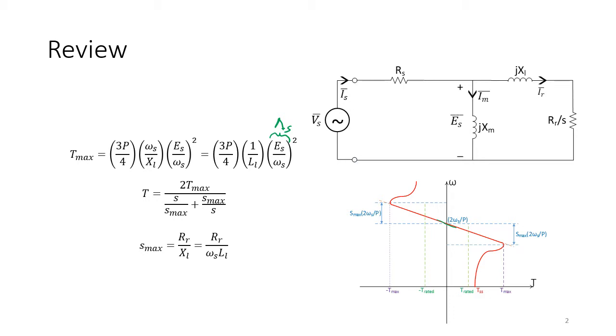Or even if it is larger but only slightly larger, your acceleration will be slow, so it takes a long time to get to the maximum torque you want. So we said, okay, one of the first issues we need to solve is how we can increase this TSS, or this standstill torque or startup torque.